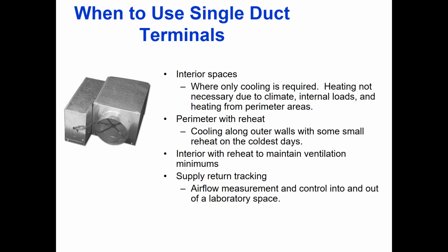Chun asked, can we have low pressure at the inlet of the VAV at all? Yes, you can use low pressure category ductwork instead of medium pressure on the upstream side of the VAV boxes. That is possible to do, and it's actually more common now that we're trying to go to lower operating pressures to save fan energy. But each VAV box that you select will have a minimum inlet pressure that is required. And we'll get to that in a little bit.